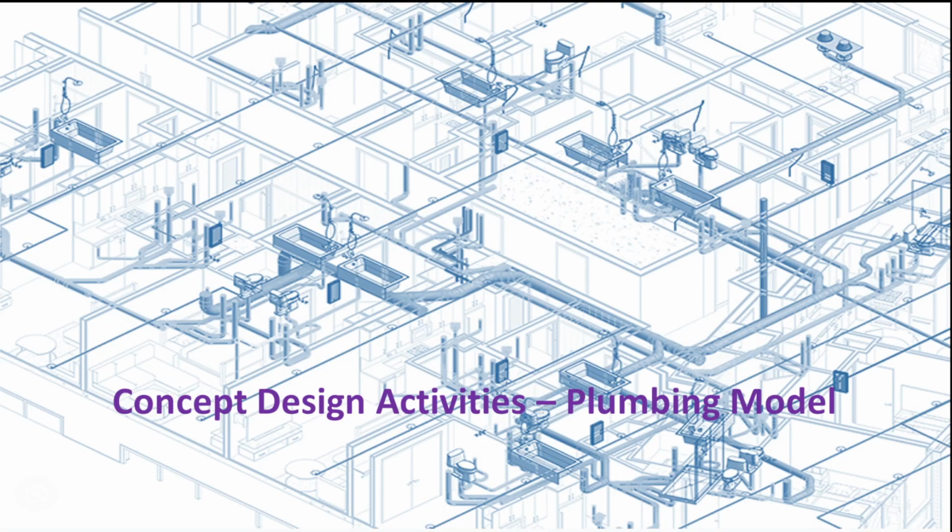Concept design activities: plumbing model. Activities that form the framework: schematic representation of existing model as a background starting point; schematic layout of major plumbing equipment represented at LOD 100 or 200, like water heaters, sinks, toilets, safety showers, and so on; approximate layout dimensions and equipment orientations.